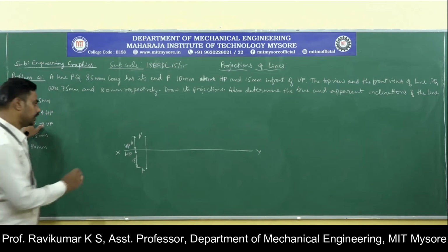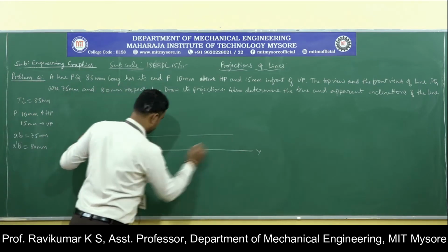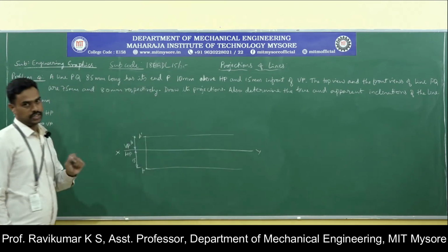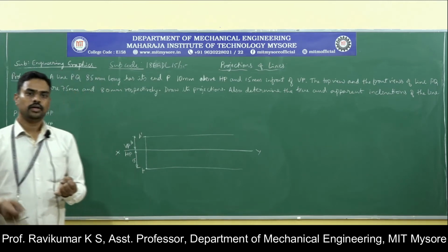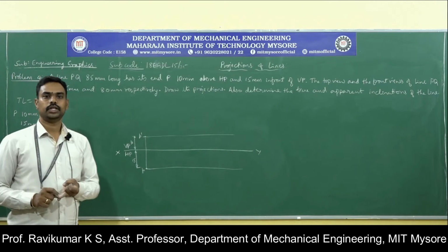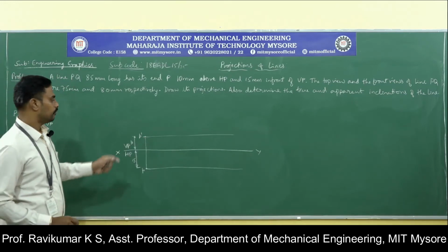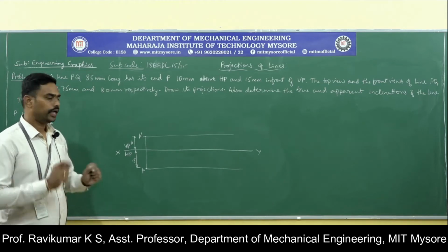Once you locate the points, you just draw the locus and be careful while writing the lines. You need to maintain the thickness carefully. Apparent length should be more thicker and true length should be medium thick, then all other lines should be thin. Okay. For thickness also you will be deducting the marks if you vary the thickness.